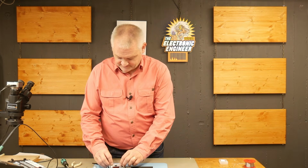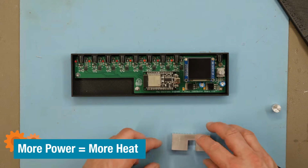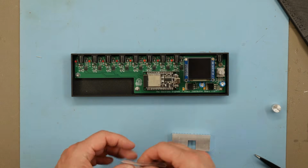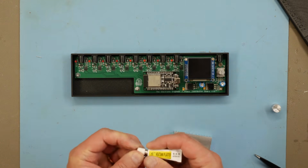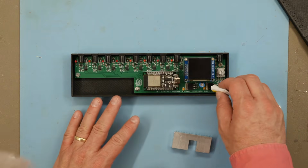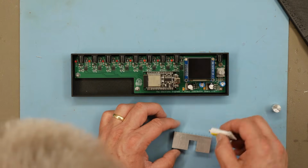So this will be mounted right here, like so. But since I cannot screw it, I'm going to use thermal glue. And this is a special glue designed for gluing heatsinks to components. It says heatsink plaster, which basically means heatsink glue. Okay. That works just fine. A little dot here, a little dot there. That will do the job.